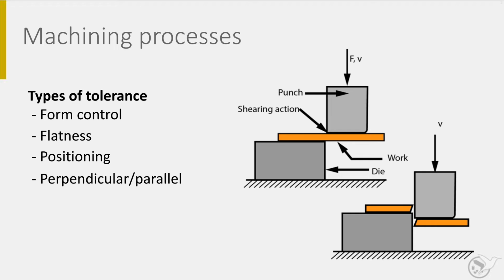Again, the plastic deformation is the main principle. First, the force indents the material, but when the stress becomes too high, the material fails in a controlled way. As for paper, the point of shearing travels along the cutting line. A variation of this cutting is punching, where the cutting operation is performed with closed loop cutting lines.